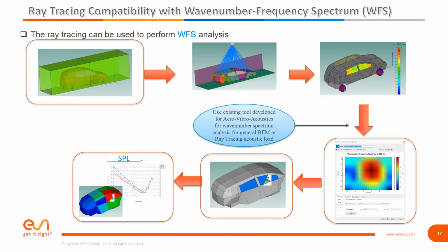You had to set up a boundary element model. It could be challenging in terms of computation to run, and then you had to sort of fit that or explore how to turn those into equivalent acoustic loads in SEA. Not anymore. You can have the full complex correlated load applied to SEA as a general surface pressure, and you can see we have a chain where boundary element component models feed large ray tracing models that can go to high frequencies, large models, fast, little effort, and you can then transform those through wave number analysis into general surface pressures, all within VA One, to the point where you can get your SEA vibration or interior acoustic responses pretty easily.